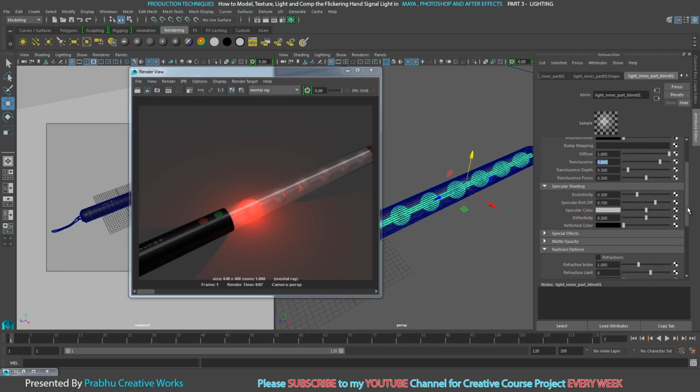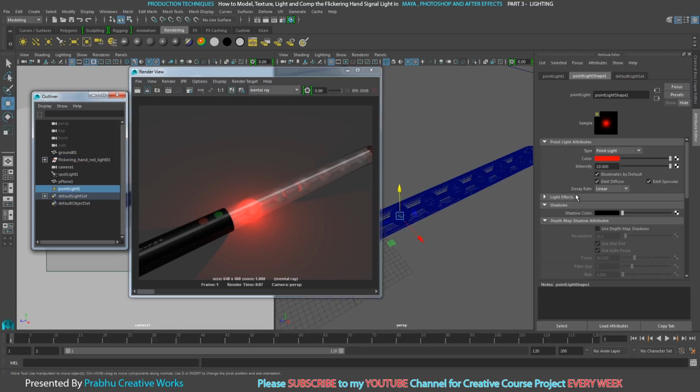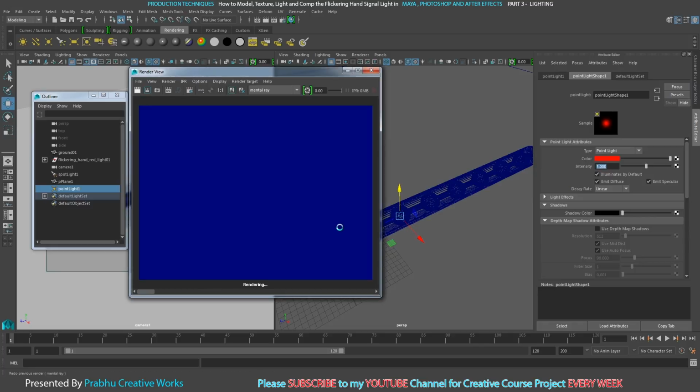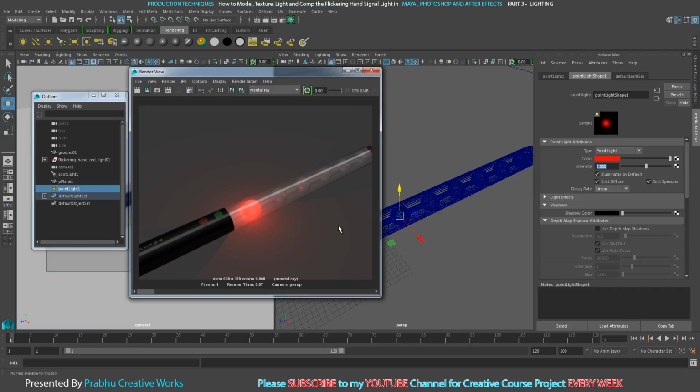So I want to reduce my point light intensity a little less. So I will select my point light. I will reduce my intensity to 5. So I'll click render again. So now I want to turn on my